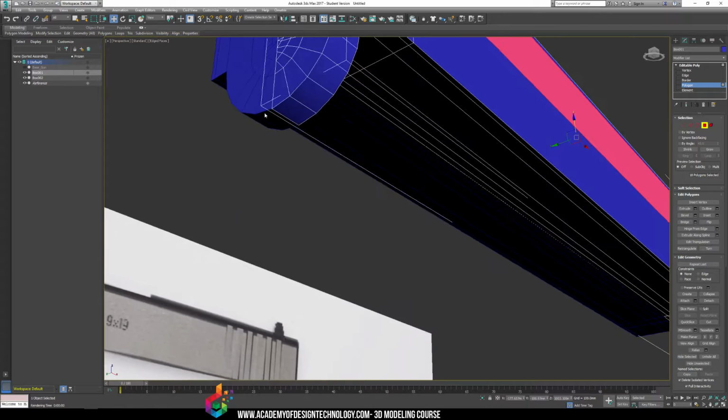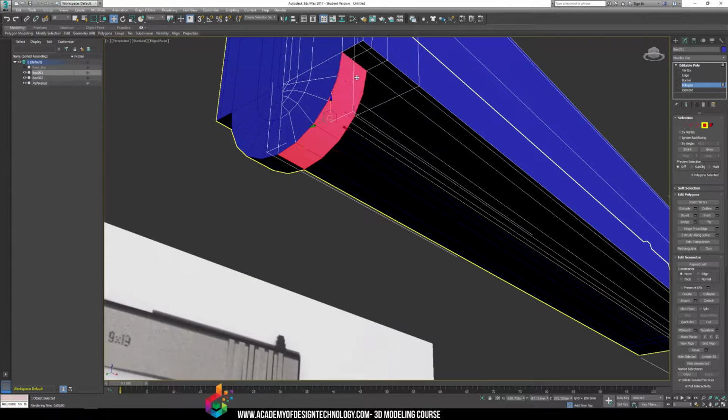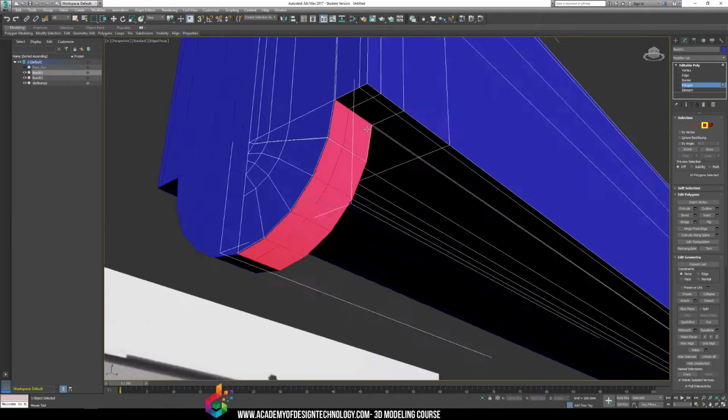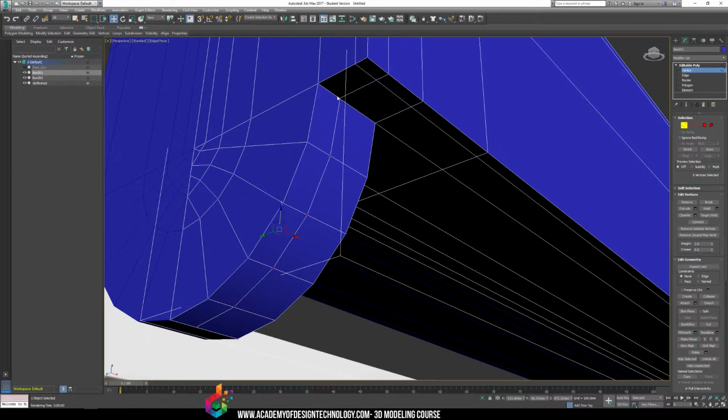And ideally what I should do here as well is I should make an edge loop. Go in with the rest of the model here as well. There's a loop that was created here. I should be creating loops that match each other. So this is where edge looping matters. We want to try and make sure that all our loops work together.